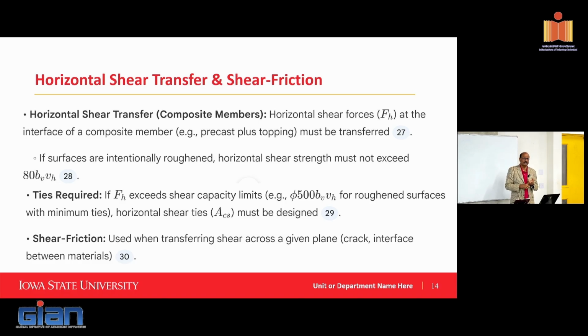Two reasons. One is that at the interface you don't have any tension, so it's zero tension. If you have a dry connection, the moment you start applying loads, that's the point where it's going to start opening up. So that's an obvious one. Then the rebar gets mobilized, then the crack will distribute. Sometimes, and we'll talk a little bit more, the connection details that you choose will prevent that crack from spreading outside of that region.